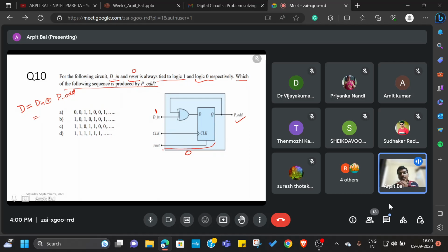If anyone remembers, I mentioned one trick during the initial logic gates classes, I think the fifth or fourth tutorial, that if you have an XOR and you have a 1 to it, it will basically toggle whatever you are presenting here, right?